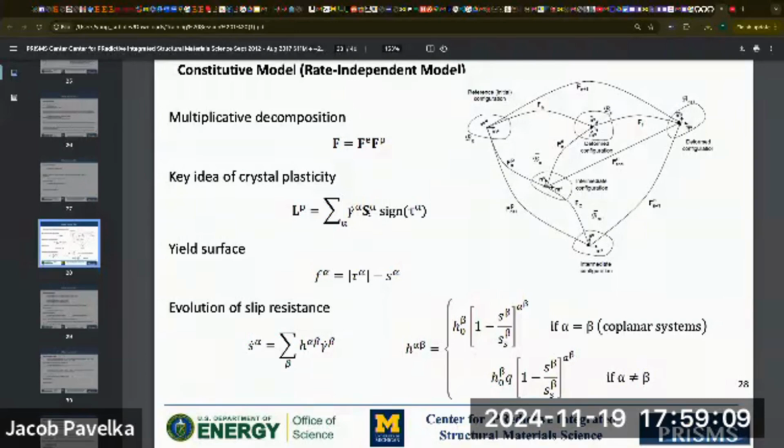Then I stretch it, and now it's from 0 to big X. We call this the reference configuration, and we call this the deformed configuration. The deformation gradient is the derivative of these coordinates in the reference configuration with respect to the deformed configuration, so some measure of stretching between these two different states of the material.